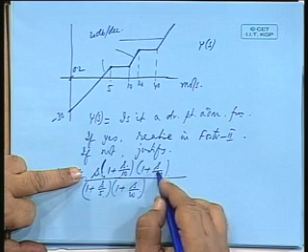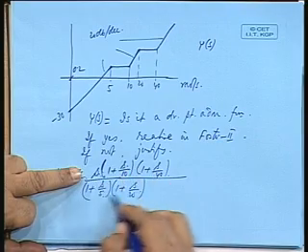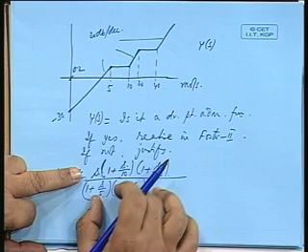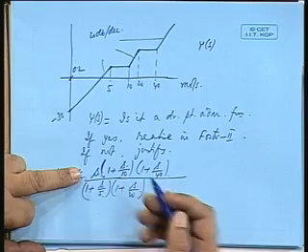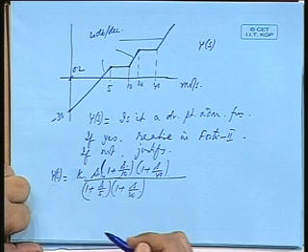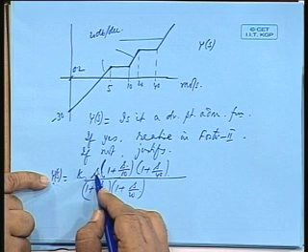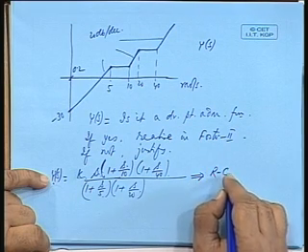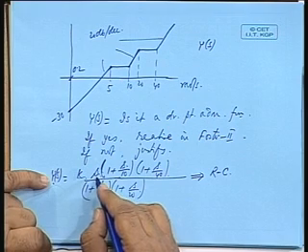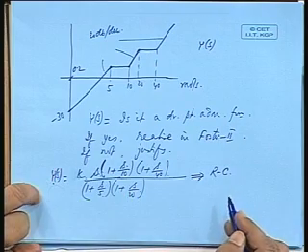If I simplify this, it will be S plus 10, S plus 40, S plus 20, S plus 5. So, if poles and zeros are coming alternately and if the difference in degree is restricted to 1, then it will be possible to realize this as RC or RL. Okay. All the roots are on the negative real axis. Is it an RC or RL? It is a Ys function and S is coming in the numerator. So, this is an RC, that is root closest to the origin is 0. If it is 0 for an admittance function, it is an RC network.